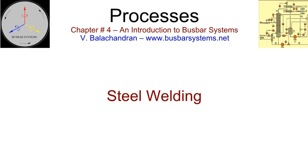Steel structures are often galvanized after fabrication. The quality of the weld is important to ensure good galvanization. It is necessary to design the support structure so that welding and subsequent galvanizing can be carried out most efficiently. In a good design, molten zinc should flow uniformly over the surface and not get trapped in the crevices during the dipping process. A good weld will ensure that there are no surface defects and there is no possibility of chemical entrapment during pickling operation before galvanizing.